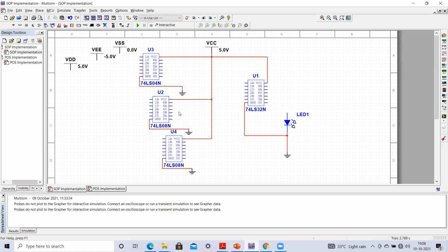So here you can see that we have to just get the complement. I have just taken this particular IC. This is our 74LS04, which is nothing but our hex inverter. From this inverter I can do the complementation part, and I will be calling this first. This is our supply. This will be used for giving variable A, this will be our B, and this will be our C. So I'm just assuming these are our input variables, digital Boolean variables.